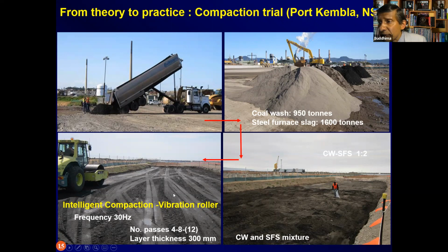intelligent compactor. And intelligent compactors are becoming very popular these days because, when they are compacting the ground, they can actually calculate the stiffness during their travel and then decide how many passes are required back and forth in order to achieve a pre-desired stiffness of the compacted ground.